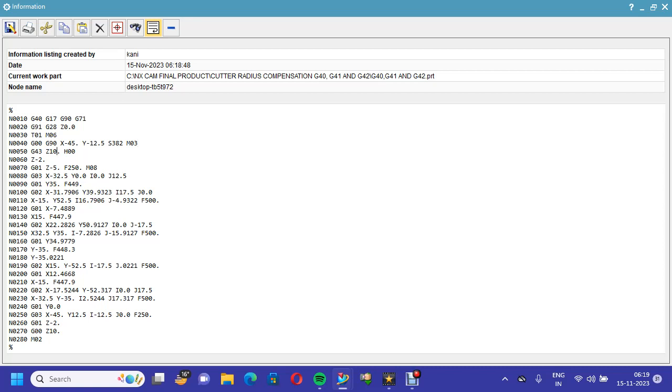You might know that we have given 10, that is G43 cutter height compensation 10. Here you can put 40 or 50. This is the height of the tool where we registered for compensation. Then it will give a depth of 5 mm once and it will complete, and after completing this it will go back 10 mm above.